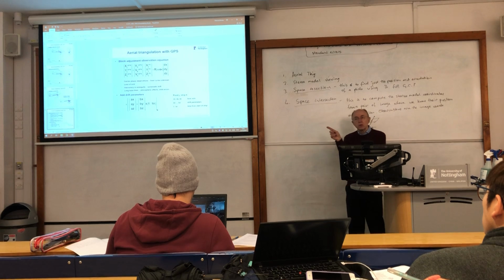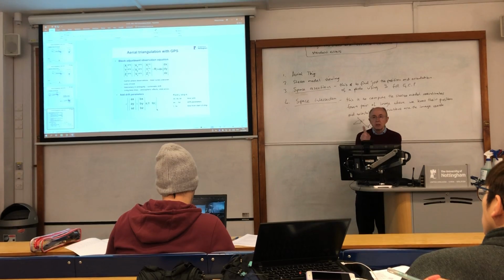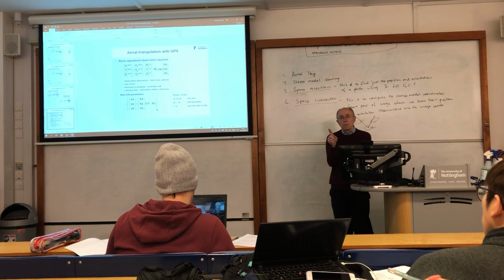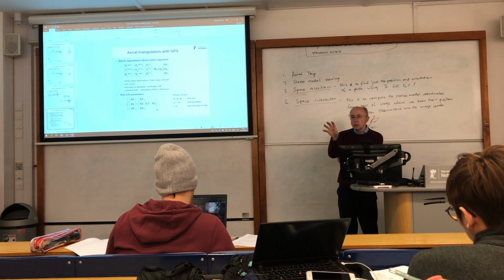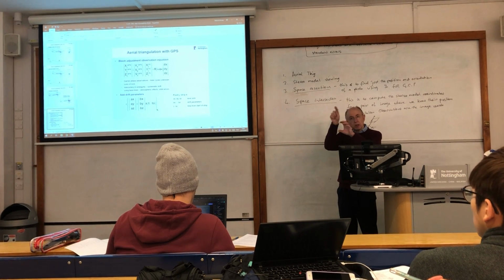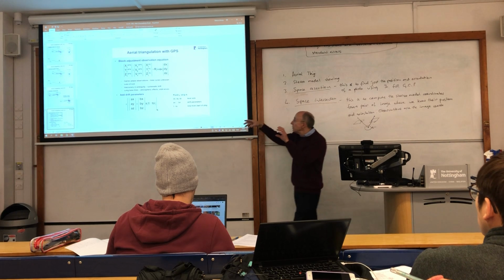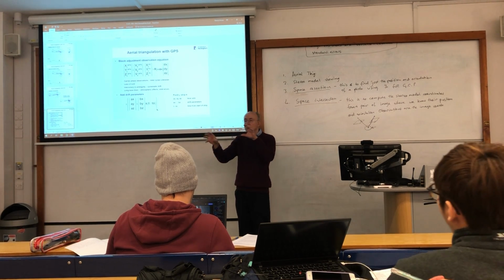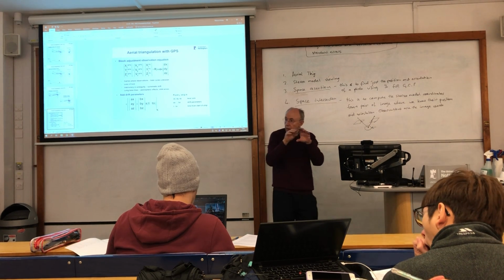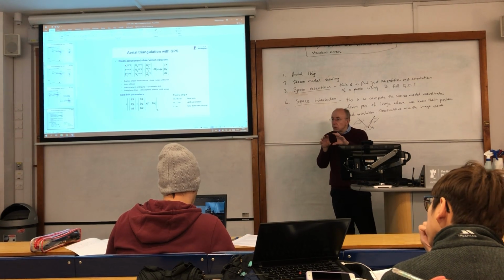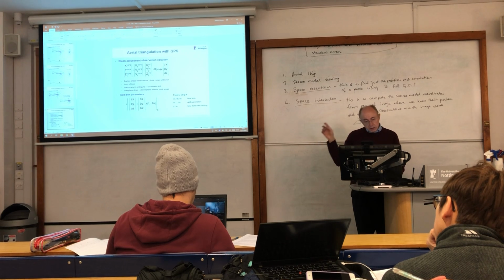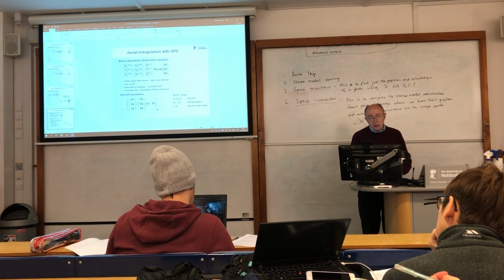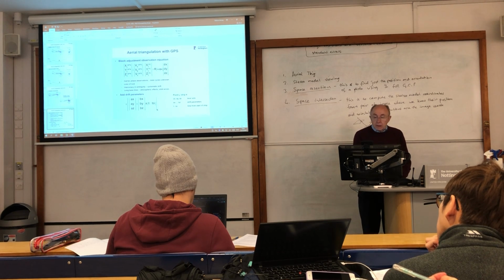Right, so we didn't do these. We put in GPS, the inertial measurement values, into the aerial triangulation, having effectively computed the lever arm relationship and applied that correction before we do the aerial triangulation. Right, so it's slightly different, but this is the general way of dealing with it. We put in some equations to deal with the GPS.